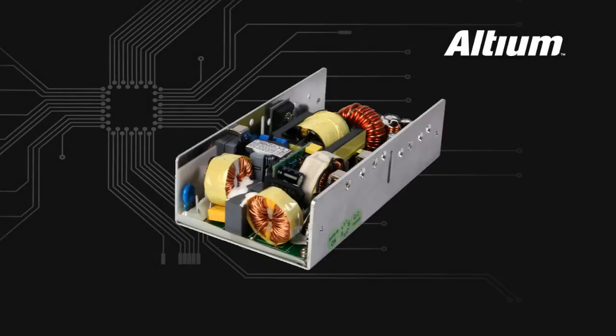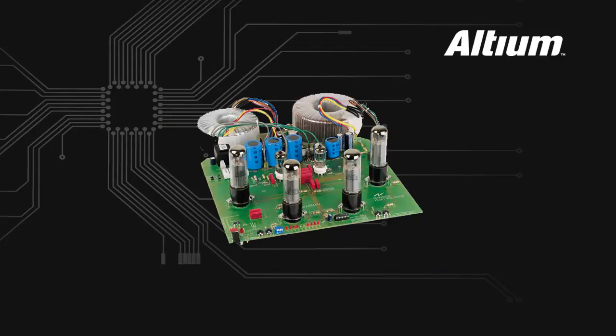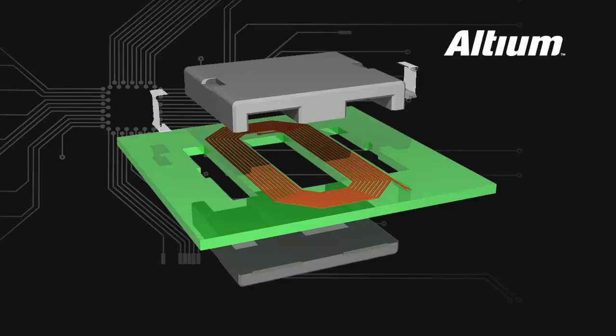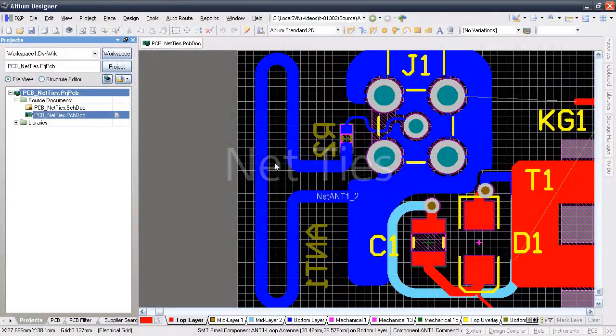Whether you design power supplies, embedded systems, RF circuits, or audio electronics, at some point you'll have to figure out how to join separate grounds at what's often called a Kelvin connection, or perhaps even use copper geometries for RF parts or planar magnetics. Altium Designer provides a very handy tool for all of these situations called net ties. The easiest way to understand how to use net ties is to see how they're made.